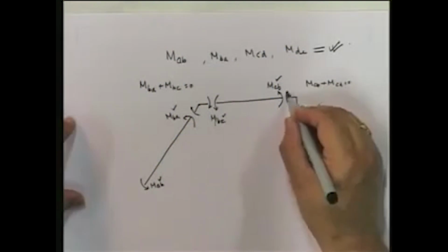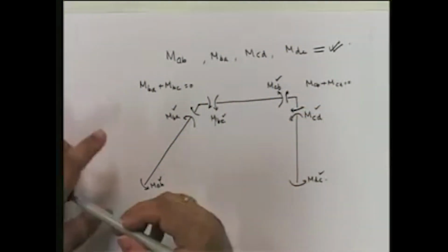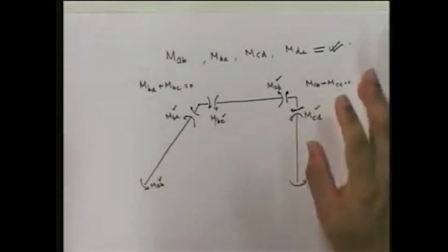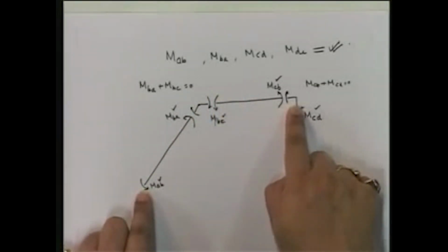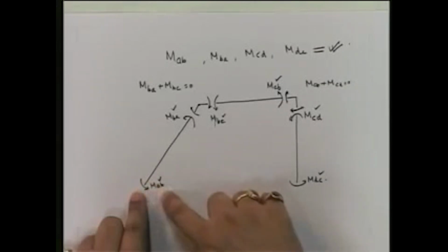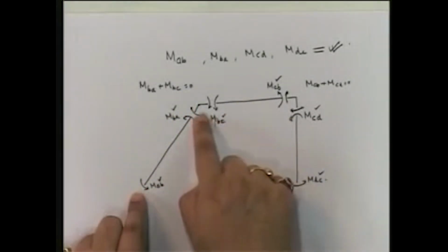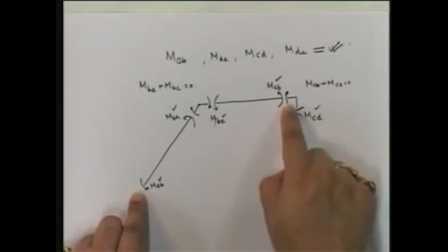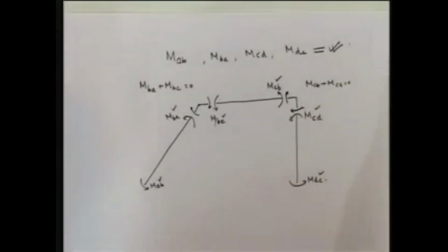Okay? So you see, the whole point here is just to go back. You can draw the bending moment. I'm going to leave that to you. I've already found out MBC. There are no member end moments, so you can always find out the reactions, and then the bending moment diagram will look like this. Straight line here, okay, continuous straight line here, come here, continuous straight line here, this way. This is your bend. And that you've got the bending moment diagram for the load of 20 kilonewton force.